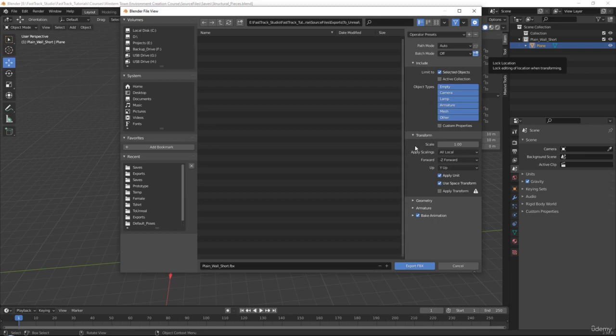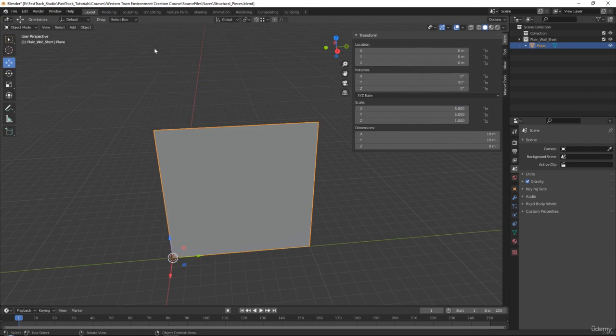And then for our scaling, often the scaling needs to be set to 3. I know this does not really make any sense, but as I said, there seems to be a mismatch between Blender and Unreal. Now I can dive into metrics and setting up specific metrics between the two programs to get everything correct, or I can literally just set the scaling to 3 and be done with it. So make your life easy. So yeah, let's go ahead and press export FBX.